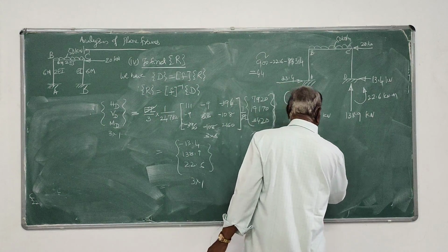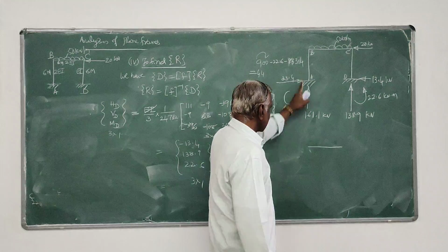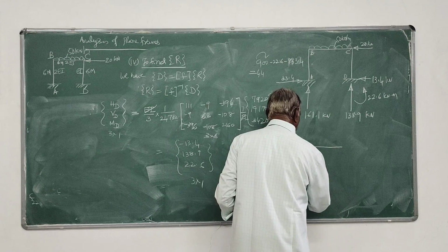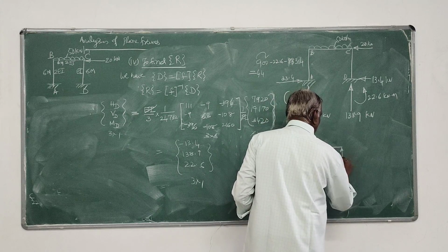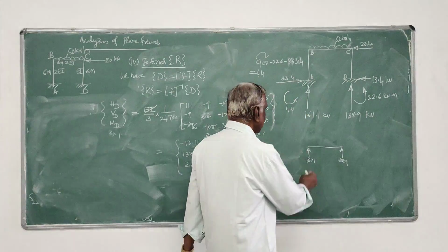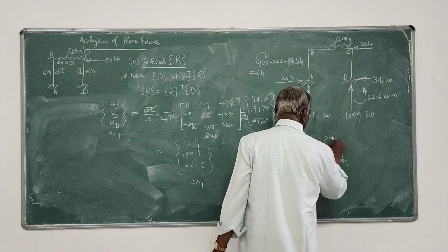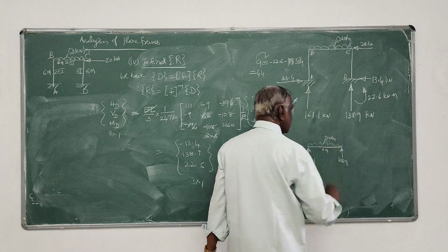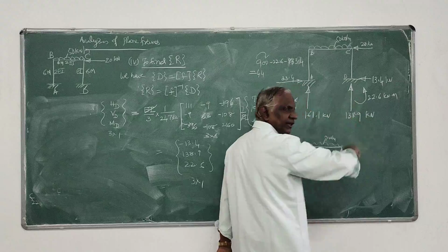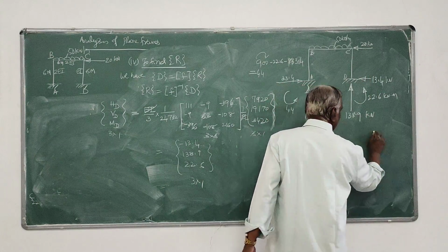Now we can plot the bending moment diagram first. So here, this is the reaction 161.1. Here 138.9. The same reaction should be there, and this is that load 50 kilonewton per meter over 6 meters. And the moment here is 22.6 anti-clockwise. Here it should be clockwise.